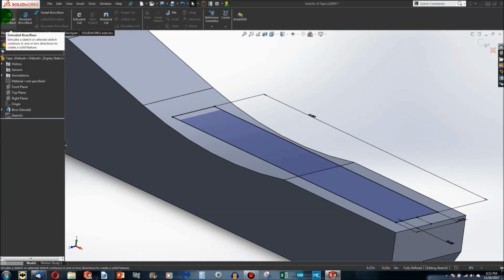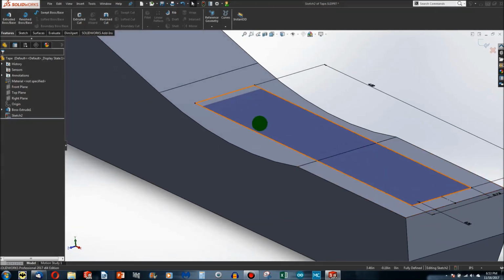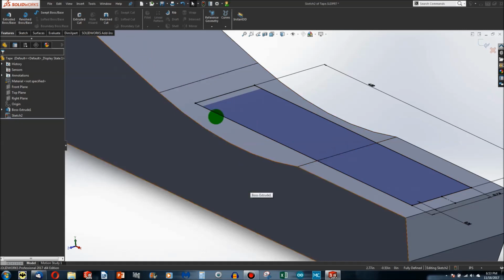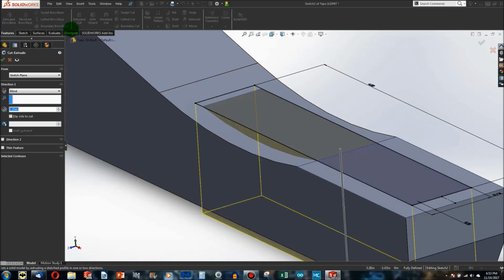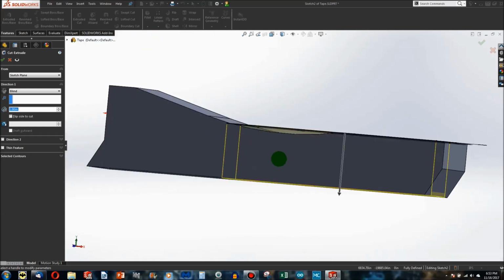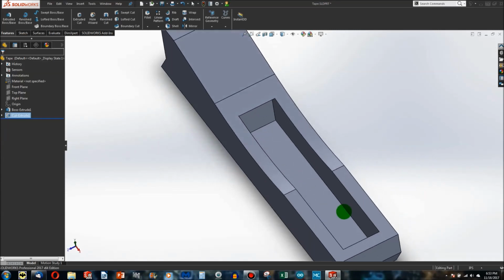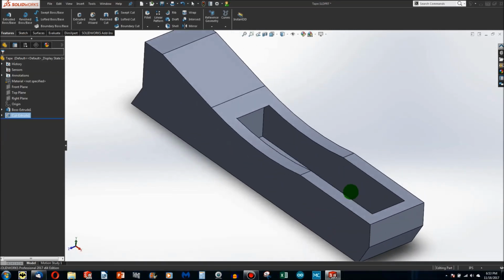And what we did is we added material from the sketch. We can do an Extruded Cut, which is the same thing except it takes material away. And what I want to do is make a place for the tape to sit in, so I can use the sketch to cut into this tape holder. I choose Extruded Cut, and it gives me a certain distance. Let's say I want to go a 1/2 inch deep. We'll probably want to go something more like 1 inch will be the height of the thing, so we'll go 0.75. And we've cut into the figure.